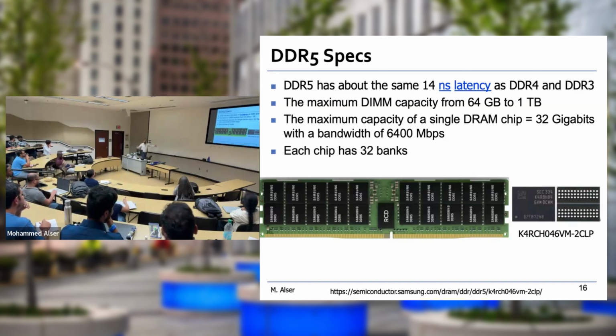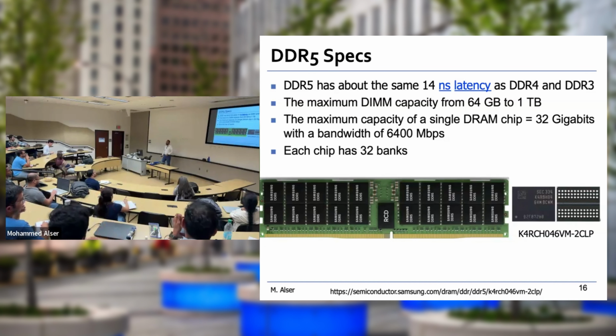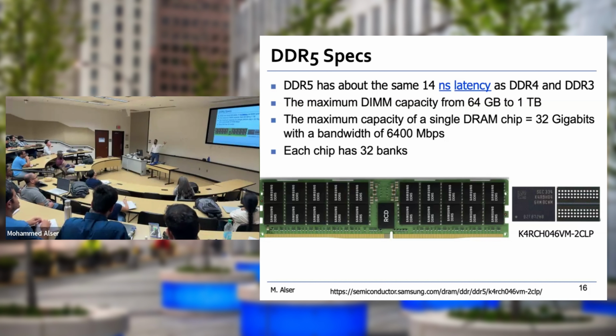So now we move from general DRAM architecture. Now let's see in closer look DDR5, which is the recent one. We said this is currently the latest version. We don't have DDR6, for example. But if you hear DDR6 and DDR7, it's still relevant, but we discussed last time, it is about graphics. It's about GPUs. So in GPUs, you can see up to DDR7, but they call it GDDR7, okay? And remember the difference between GDDR and DDR is only the number of pins in the chip itself. So a single chip, instead of giving you only 8 bits, they give you much more than that.